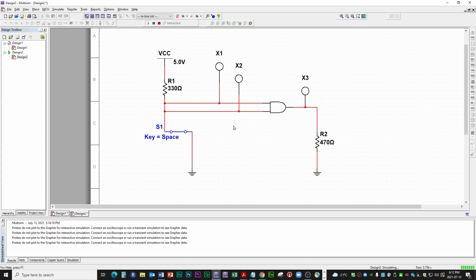Right, so let's just stop the simulation right here, because anytime you want to change something about the circuit, you gotta stop the simulation. So click, that thing becomes green, which means it's ready to be pressed. All right, now let's just get rid of all the connections over here at the input. So I'm doing that, selecting those lines and pressing delete, clicking on those lines, pressing delete. So we got almost a fresh input start here.